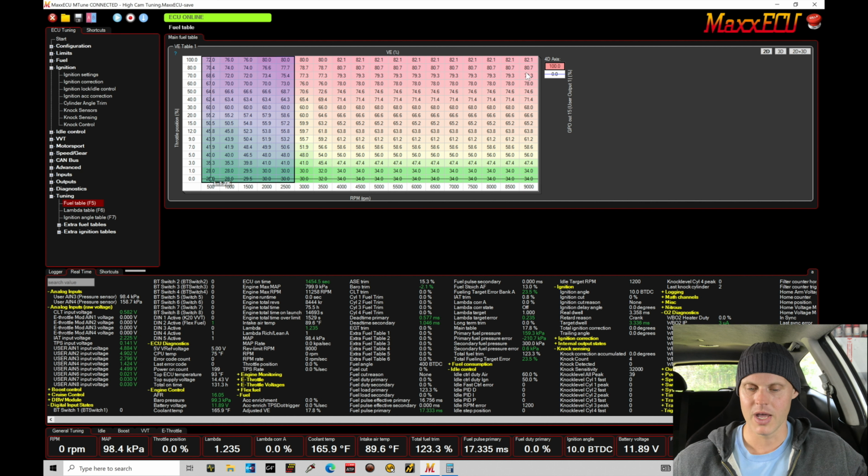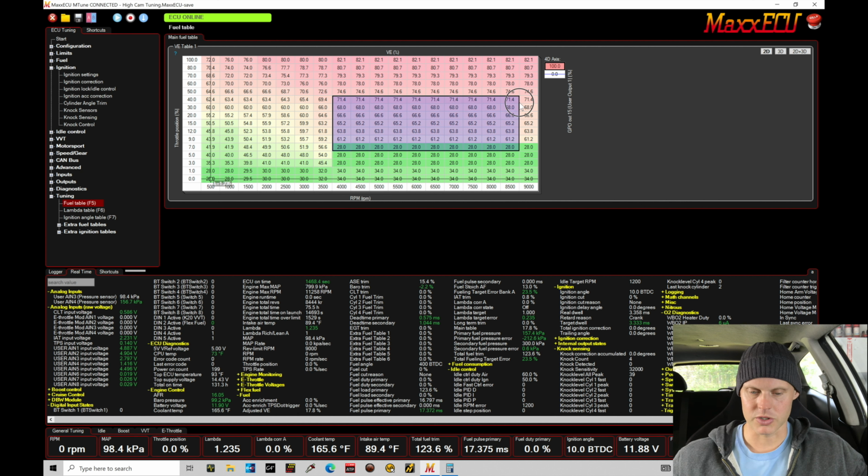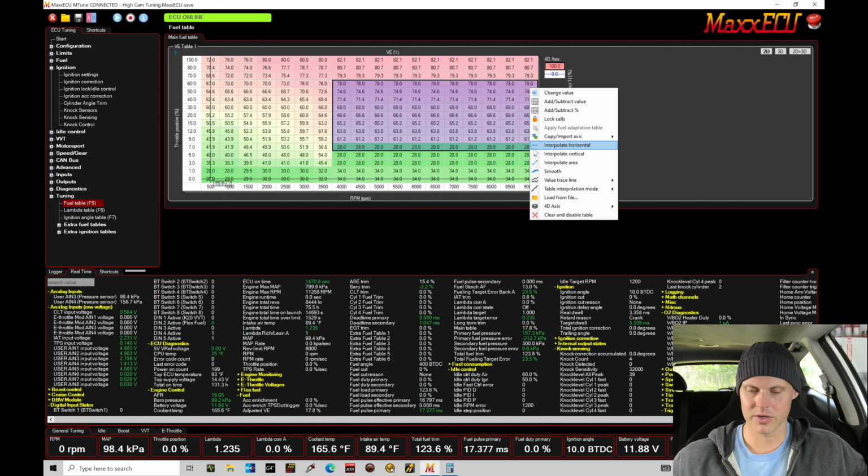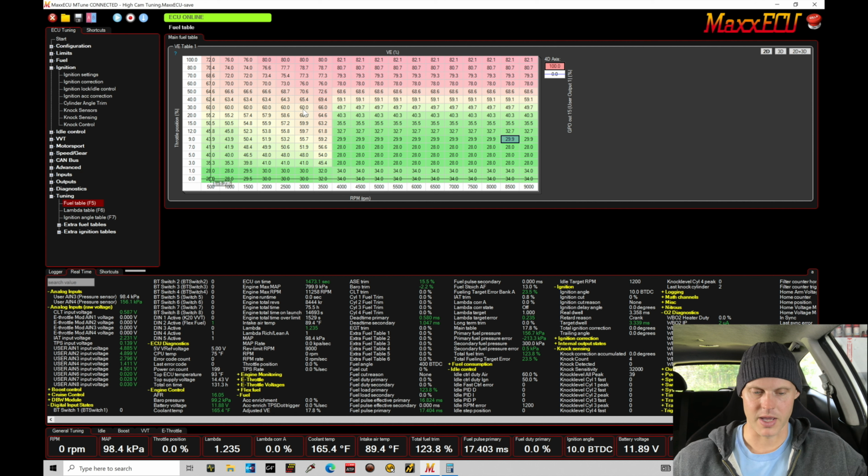Now in part throttle, we should also match up what we're finding here. At very light throttle, we're finding about 20 to 30s. If we use that same functionality here and set this to something like maybe 28 right here, let's go ahead and edit our values in our table and do an interpolation upwards. We should find similar fueling to that low cam, and then we can do a little bit of horizontal interpolation across here, kind of blend this in. So this should be fairly close. We might have to touch that up in the part throttle. We'll have to see how that goes, but we should have at least the same VE values from our low cam to the high cam. So hopefully it makes sense.